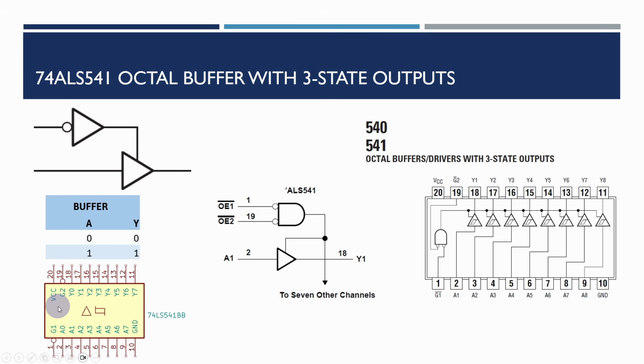And this is the symbol from KiCad. In the diagrams that I use in KiCad, what I've tended to do is to change these layouts. So quite often the chip layouts are arranged logically, with the inputs on the left-hand side and the outputs on the right-hand side. Now, in fact, on this chip, pretty much all of the outputs are on the right-hand side, apart from this G2 select output enable. But what I tend to do is to make sure that the chip layouts actually match the physical chip layout, because it means that our schematic diagrams can then be used as the physical board layout diagrams. And it's just less likely you're going to make mistakes when you see that a pin over on this side is being wired up, when in fact it's physically over on this side.